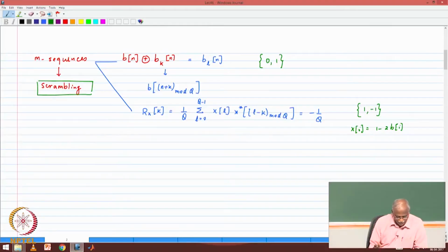Scrambling versus encryption. Okay, the point that was mentioned was that scrambling means the order of the bits has been changed. In our notation, particularly the way it's defined in CDMA 2000, scrambling is slightly different. Basically, you do a modulo 2 addition with another sequence. So you have the original sequence and a modulo 2 addition. Let me just write that down.